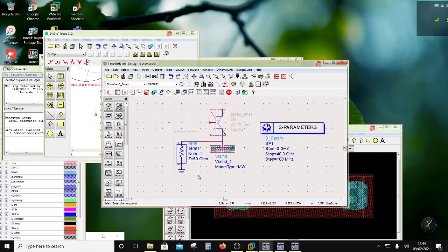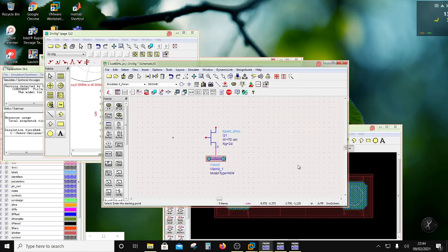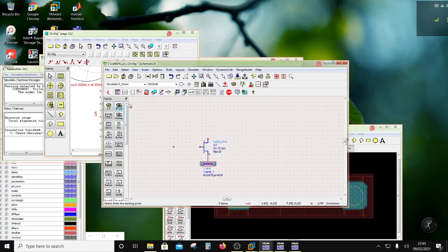So now let's do the DC simulation. Okay, so this I have enabled, and I'm not going to do S parameter. I'm going to do DC simulation. I'm going to put here two inductors. Now people will put here what is called a choke or a DC feed, but I'm not doing that for a reason, because if the transistor is oscillating, my DC currents are wrong. But if I put an inductor with a loss, then there are more chances of this being stable. So rather being inaccurate is better than being totally absurd, right?